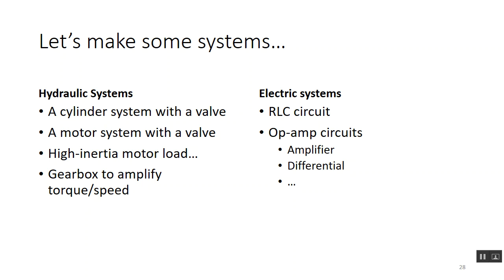The things I've done with Simscape have mostly been electrical, hydraulic, and mechanical, because you're motivated to do what you have to do most of the time, and that's the stuff I needed to do. I had analog signal processing, so I did that with op amps and did the modeling using Simscape, making models of whatever fidelity I needed of those op amps. Some of it was SPICE models, some of it was less complicated ones.